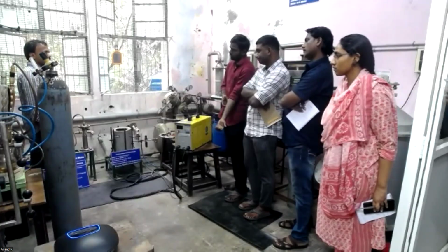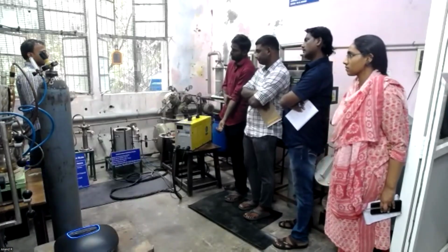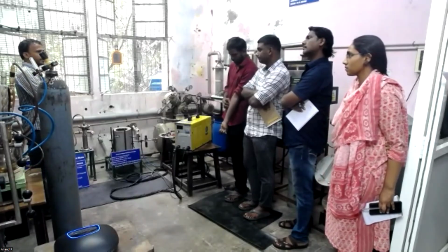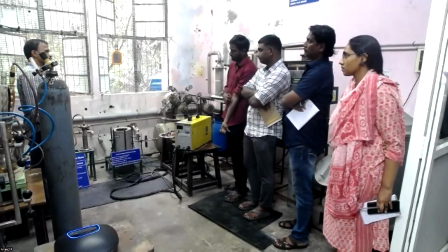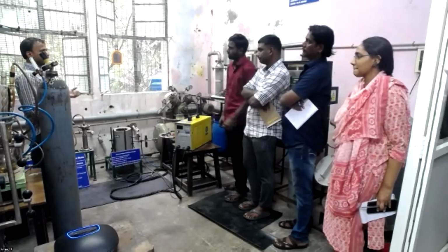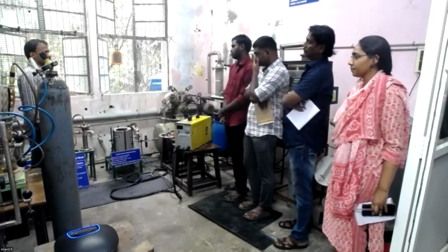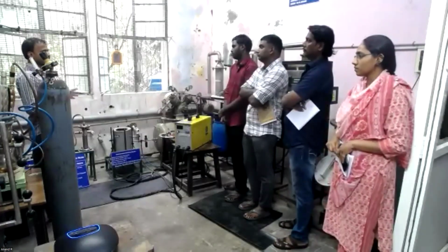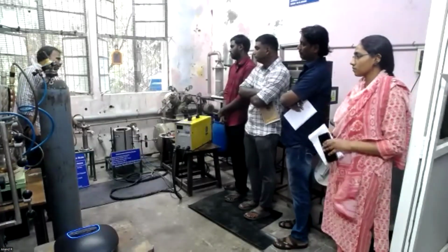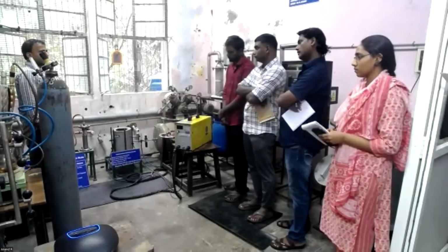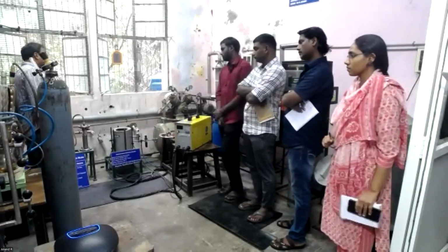In the wet scrubber, we are scrubbing HCl or some other pollutants. You can use any wet scrubber, or else water may be used. So water may capture the nano-sized soot. Here heavy particles are collected, and the syngas is completely cleaned. Then this is the mist eliminator.